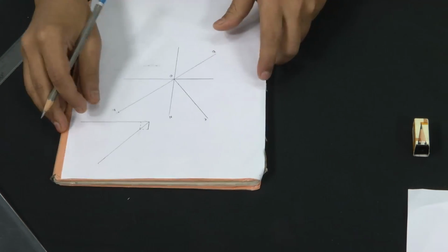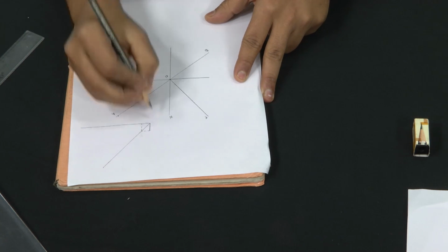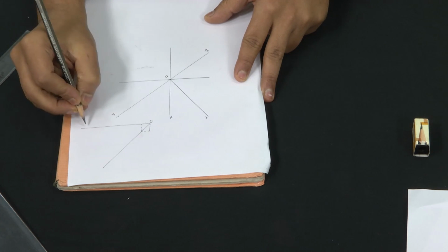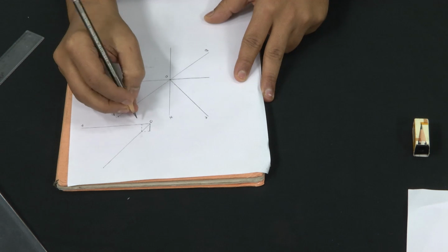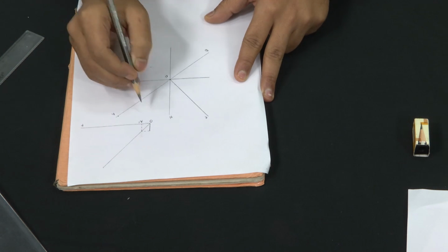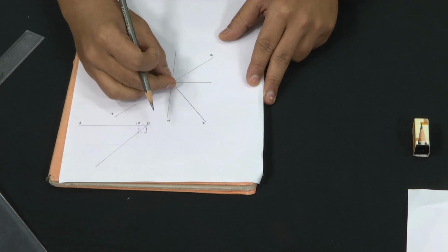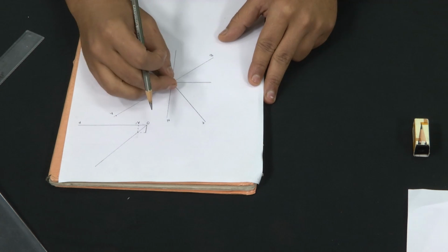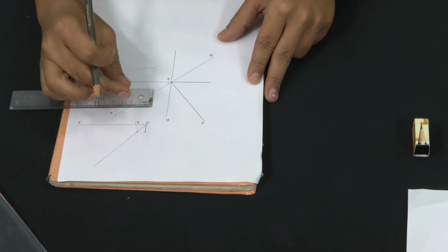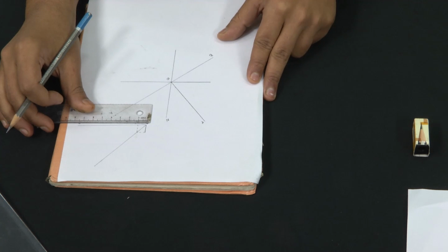Now, I again rotate to bring it to the original position. So, suppose this is my OP line, and clearly this point I can call A dash. So, OA dash is the distance in the OP line to construct our 100 meter strike line or the stratum contour, because OA dash is the horizontal plane spacing of the 100 meter strike line.